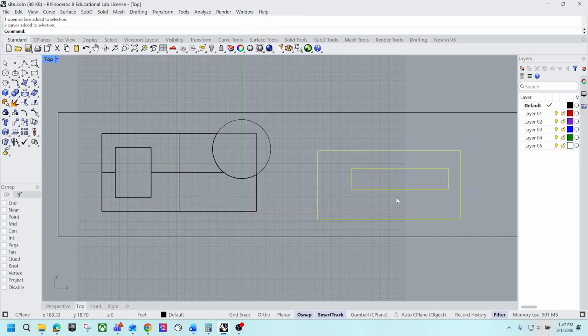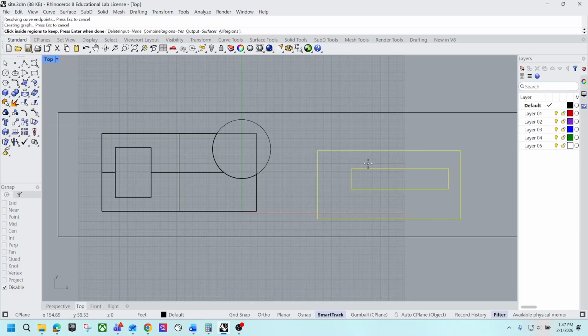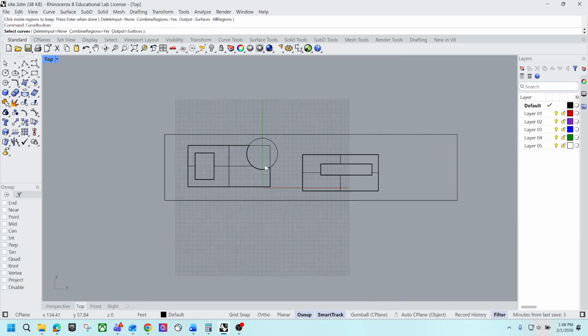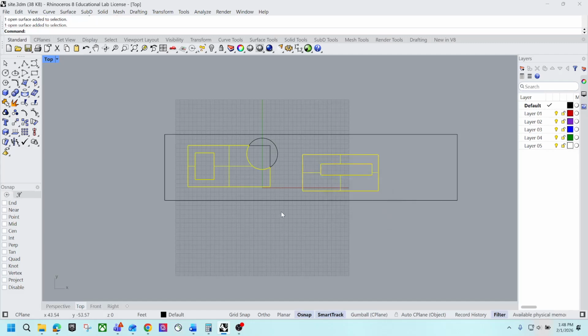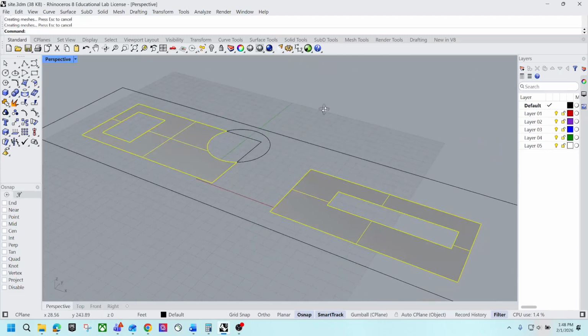So the same thing, I can do the curve boolean one more time, and I can pick up these two curves, and I pick up points in the middle, enter finish, right? So basically what I have now is these two patched surfaces, right? So I will change this to 3D view. It's easier, you can see they are right here.